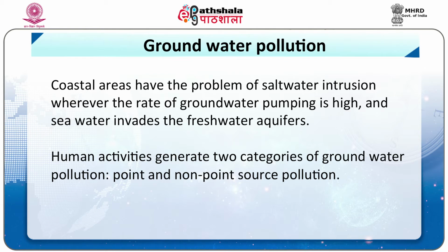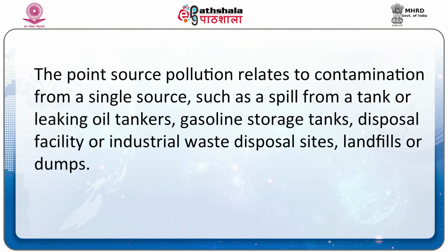Human activities generate two categories of groundwater pollution: point and non-point source pollution. The point source pollution relates to contamination from a single source, such as a spill from a tank or leaking oil tankers, gasoline storage tanks, disposal facilities or industrial waste disposal sites, landfills or dumps.